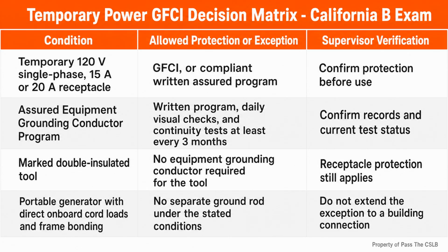Concrete-encased electrodes, often called UFR grounds in the field, are a sequencing issue as much as an electrical issue. The grounding connection depends on reinforcing steel that remains electrically continuous before the concrete is placed. The source material identifies standard steel tie wires, exothermic welding, or other effective means of making that reinforcing steel continuous. Plastic ties can hold bars in position, but they do not create electrical continuity. That is the distinction a general building contractor has to catch.